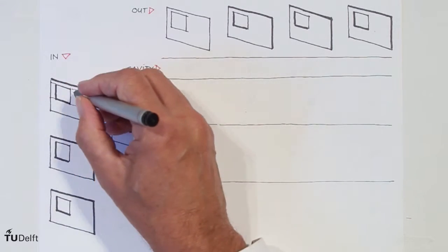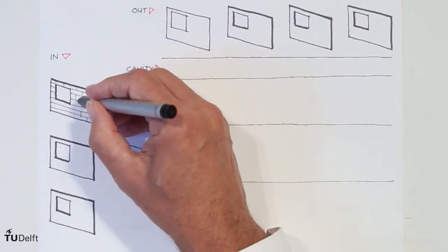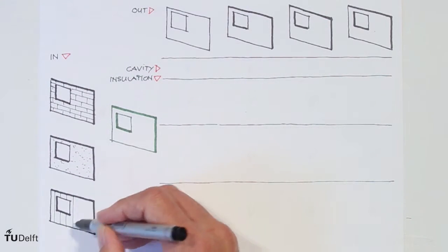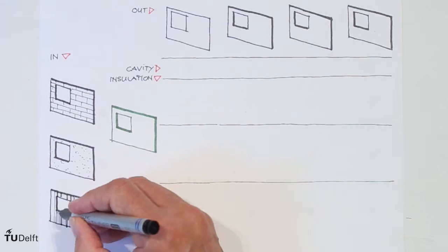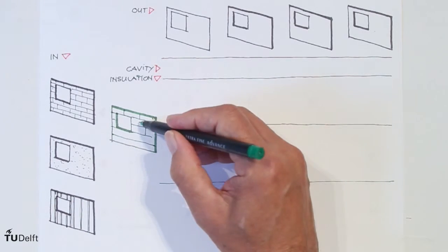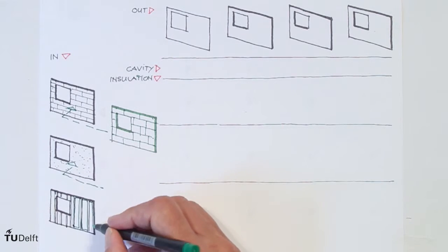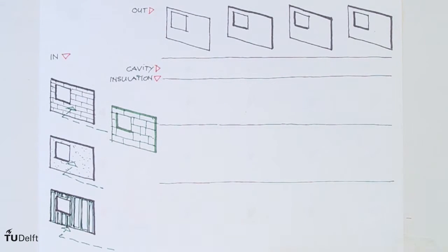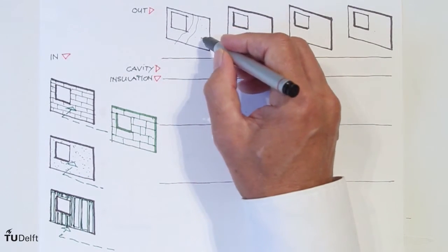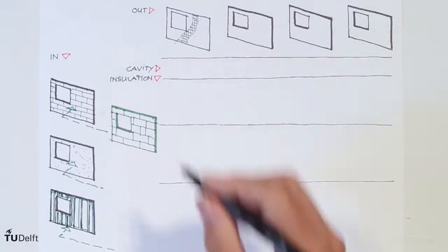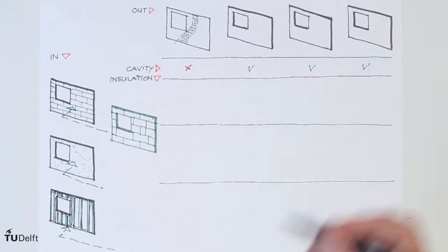To conclude, we discern 3 types of structural layer: blocks, plates and a system of studs and infill. Thermal insulation has to be applied onto the block wall and the plate wall and into the stud wall. Extra thermal insulation can be applied on the stud wall. As outer layer we discern 4 types. The first is a layer of glass fiber reinforced stucco directly applied on a smooth thermal insulation.